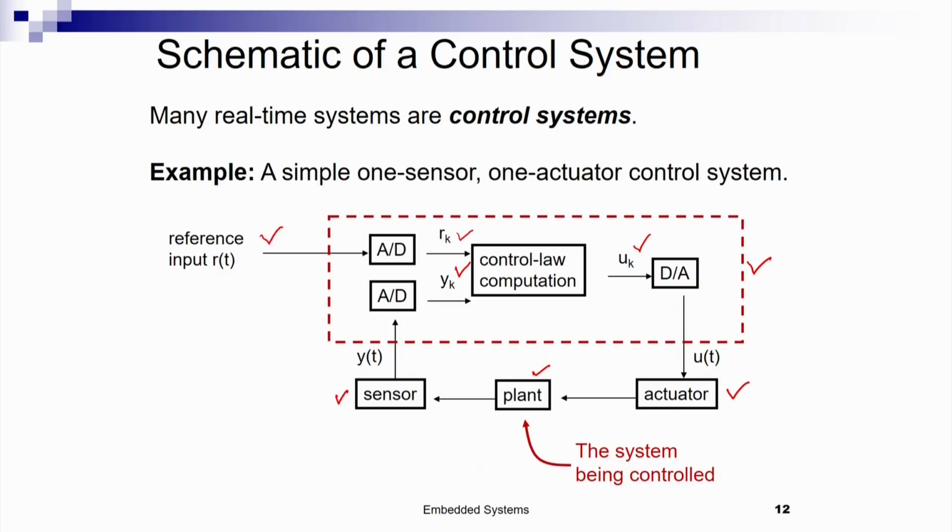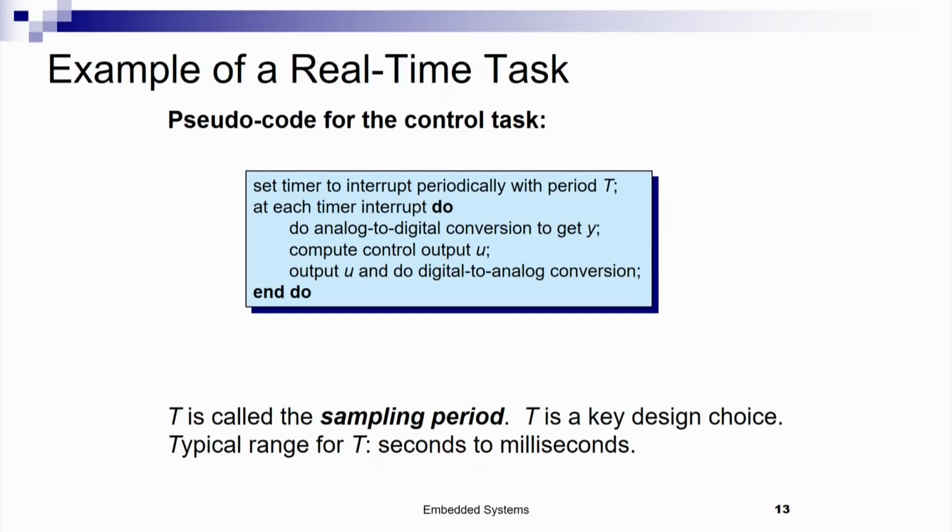Again we go on checking what is the current speed, what is the desired speed, what is the error, and what should be the throttle, and this goes on in the control system. And this controller, if it correctly functions, will be able to effectively control and maintain the speed at around 40 kilometers per hour.